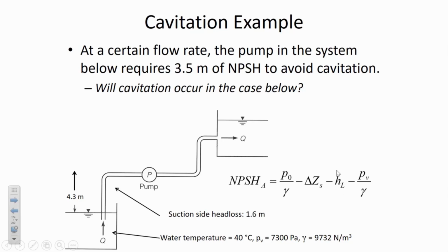How does water temperature affect the risk of cavitation? What's more likely to cavitate, warm water or cool water? Warm. How come? Lower vapor pressure? Close. It's because warm water has higher vapor pressure.